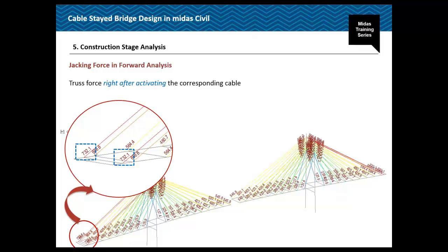This value represents the jacking force which should be applied in the installation stage in the real construction. So we should not be confused between the pretension force entered in the model file and the jacking force. They are not the same value.